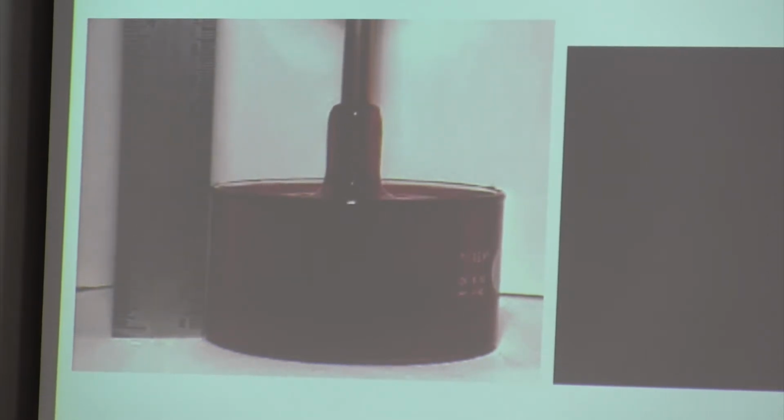And this is what is called an effect of normal stresses. So in this case, it's again flexible polymers that are stretched along the streamlines, and as the streamlines form a closed circle here, it's like a pressure that will push fluid inwards and the fluid will move up there.